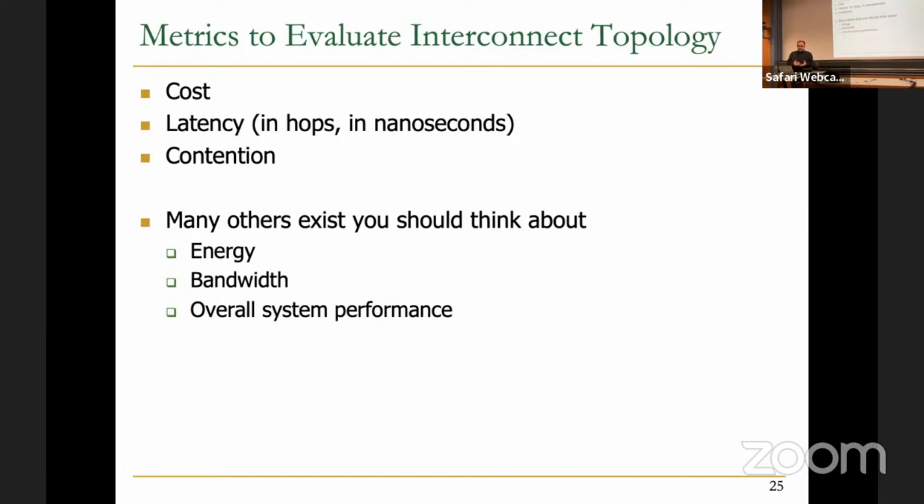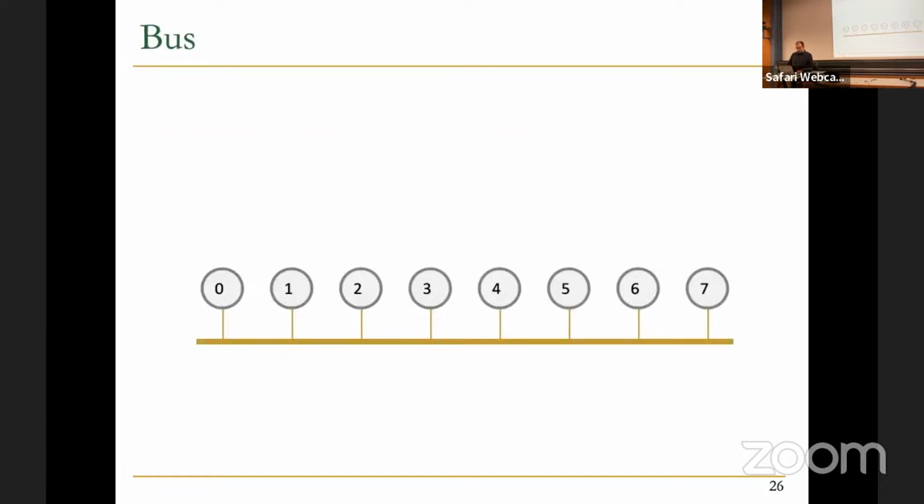But if your network latency is around, let's say, 1,000 cycles, and then you reduce it to 300 or 400, then you can observe some performance improvement. So it's always important that you also see, or at least analyze, the effect on overall system performance. This part, I would say, in early research in this area, people actually forgot, or they simply didn't focus on. But later on, people started to report system performance metrics as well in interconnection works.